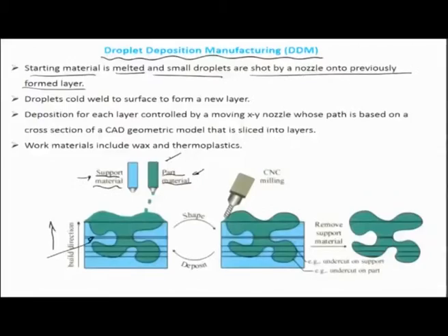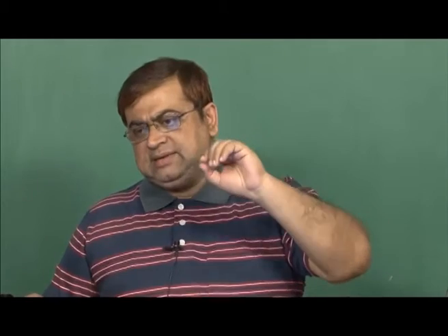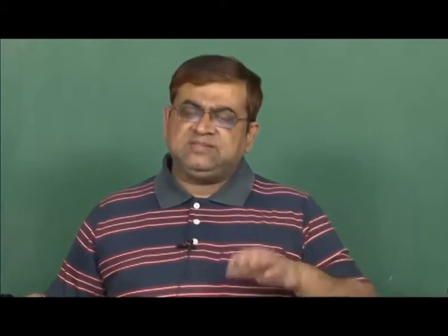Okay, the wax is just a sort of housing for the final part geometry which is going to get created. So the first step here is that you develop a precision XYZ stage to have the part material follow a CAD package. So let's say there's a slice plot coming from the CAD of a certain 3D geometry, and the slice plot has certain areas along which a nozzle has to be guided, or let's say a dispenser has to be guided.